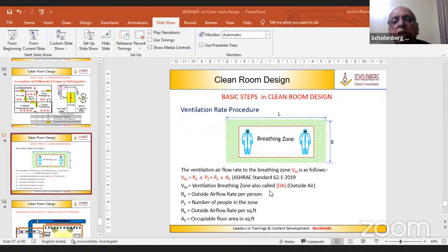Can you tell us in short, how do humans work with low RH areas? I won't be knowing how humans work. Low RH will result in dry skin. That's it. Normally, wherever there are human beings, they have a comfort RH, right? Comfort RH is 50 to 60%. Below 50, it becomes dry. Below 50, it also results in static electricity. That is also defeated now, no longer required.